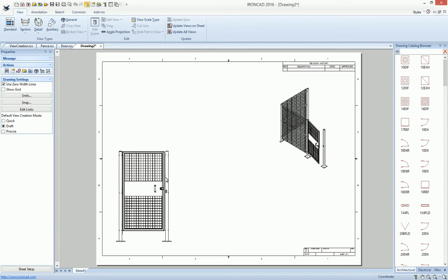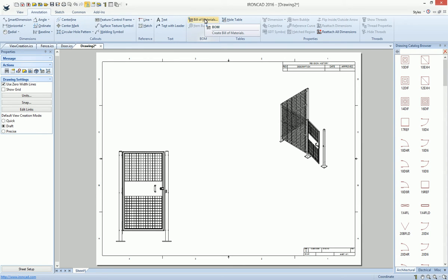You could always create different configurations in the past, where you could say this is view 1, configuration full assembly, view 2 door assembly. You can go and create those configurations in your 3D and do that, and then create BOMs based on configurations. You can do that. Now we provided another way. You could have multiple parts, different files inside of here, and you can basically do a bill of materials based on the view, or what's visible in that view. So you could have even one scene, something suppressed, not suppressed, and create your bill of materials.